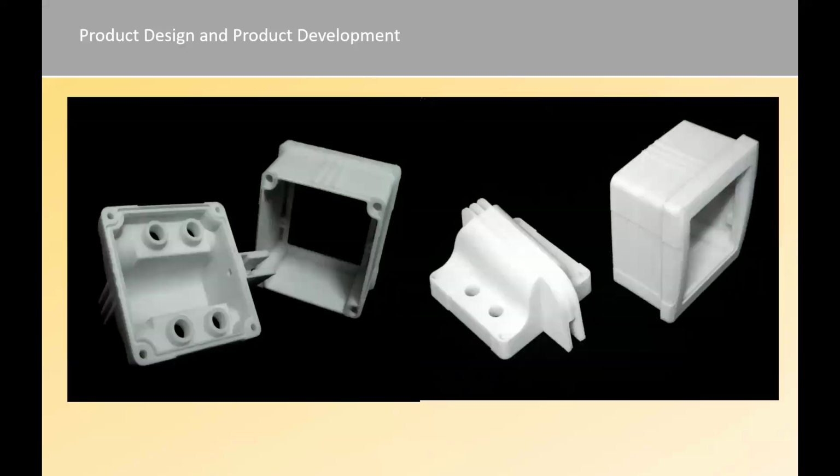So this was the prototype which was tested on the field, and we tested it for UV exposure. We tested it for water, rain, and dust protection. We had this ultrasonic welding in the front, where it could be a touch screen, a rubber keypad, or just an LCD display, for power saving applications. One of these variants was an RF model where only messages could be received on your mobile phone.